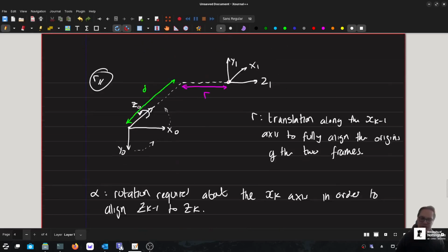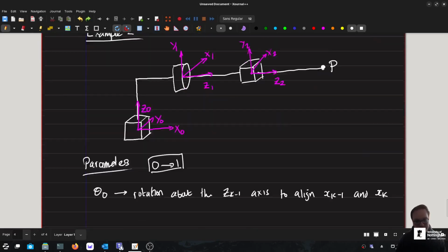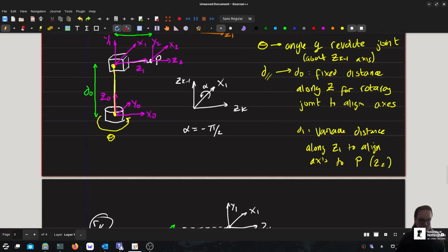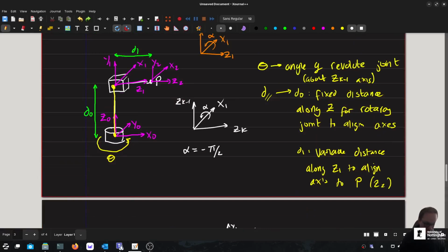So I know before I mentioned it's just a rotation. Technically it is. So you can see in this case there's going to be a 90-degree term already, and then there's going to be a further rotation for that one. If we're doing theta in this case, it's an important thing to mention here. First and foremost, we're rotating about x0, so the first thing we need to do is align x0 and x1.